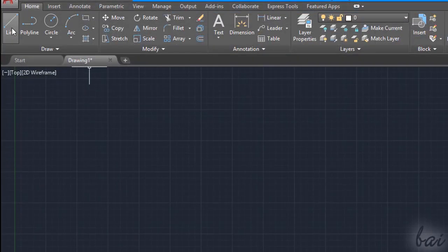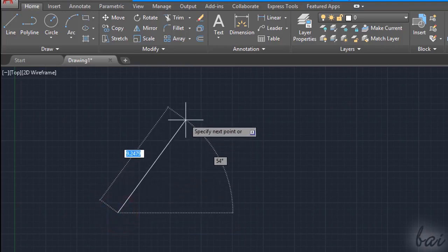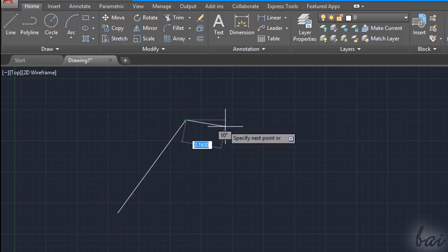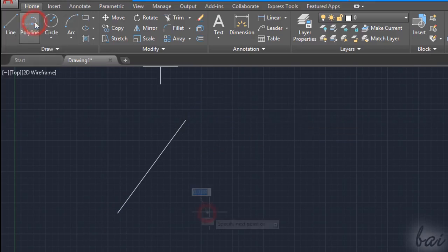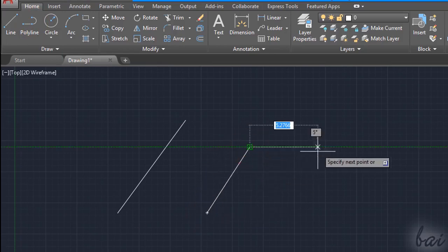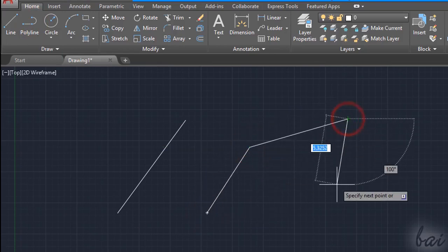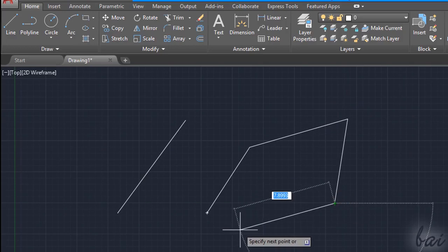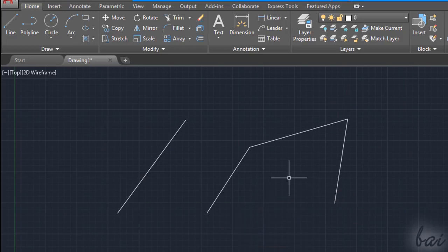Click on the Line or on the Polyline tool to draw lines and segments. Click once on the workspace to fix the first node, and then click once again to set the second node and create the segment. In this way, you will drop consecutive segments sharing the last node as you click on and on until you use the Escape key.